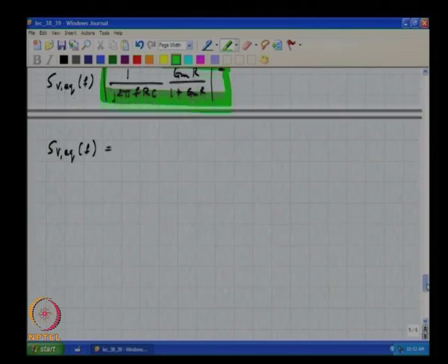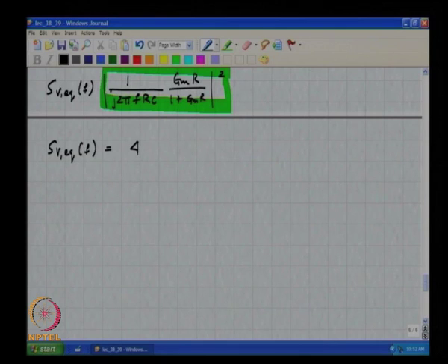So, you get 4 k t r. This makes sense because the noise source corresponding to the resistor is at the same place as the equivalent noise source that you are trying to find. So, it is no surprise at all that 4 k t r appears.